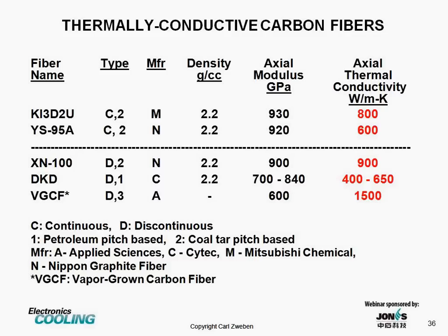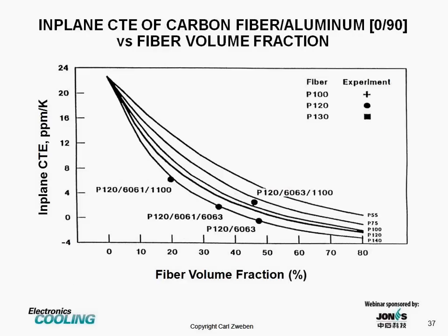The bottom material, VGCF, stands for vapor-grown carbon fiber. These are fibers made by a type of chemical vapor deposition process. They're discontinuous, but again have thermal conductivities up to 1,500 watts per meter Kelvin.